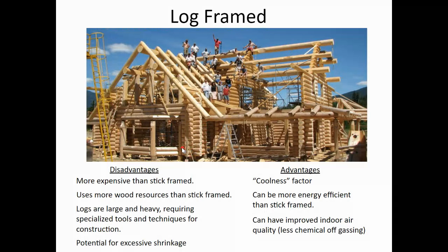Remember, we said over the width the board can shrink 8%. What happens if all these boards just shrink a little bit? The whole wall is going to shrink a little bit, and that could cause a problem with maybe windows and doors. They won't open and close properly.